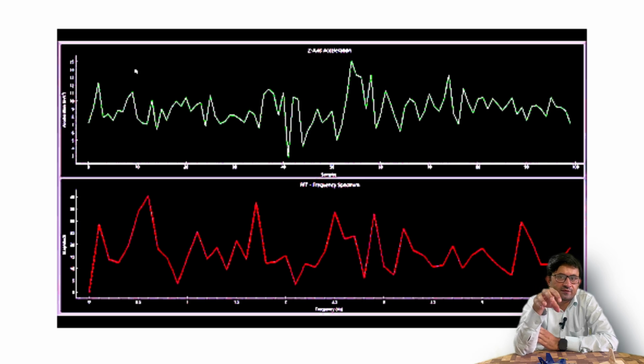So this kind of acceleration, plus 6g and in negative minus 4g. At this acceleration, the control surface may break. Forget about controlling the aircraft. If you face this kind of acceleration, flutter, you will not be able to control the aircraft. And forget about controlling, it may be completely cut off from the structure. For example, let's say this is a wing and this is a control surface. If this kind of phenomenon happens, the elevator may break.